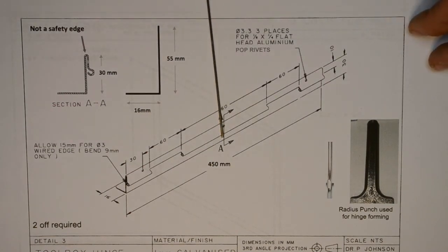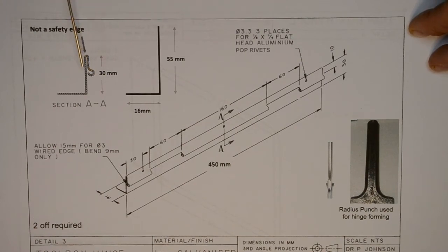Without this particular line here giving us this sectional drawing that we've got up the top here, we wouldn't really understand how that curved part forms, how we have a self-securing joint here with a 1mm gap, and how it then goes down and folds out to make the lip for the shelf that goes into the top of the toolbox. That's a critical point, that section AA. Without it, we would have no idea how this whole process goes together to produce the hinges.